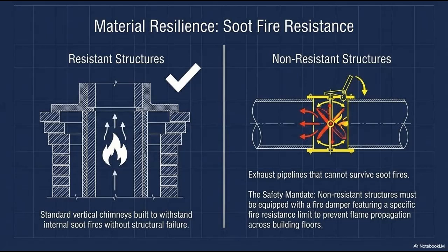That preheating action serves as a highly efficient built-in heat exchanger. The boiler no longer has to waste expensive natural gas heating up sub-zero air. The air arrives pre-warmed by the waste heat of the exhaust. That's incredible. And simultaneously, that cold incoming air acts as a constant insulating jacket, drastically cooling the outer skin of the entire pipe system. Which makes it vastly safer to run through the internal structure of a multi-story building. You don't have a blazing hot pipe pressed up against wooden floor joists.